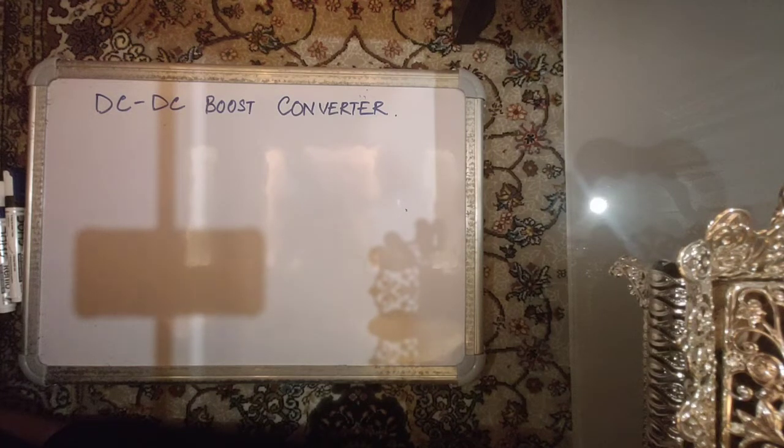We resume our lectures on advanced power electronics. In the previous lectures, we have started with non-isolated DC to DC converters and predominantly discussed the buck converter in detail with the design of passive elements, the role of switching frequency. We have done waveforms for CCM and DCM and the boundary condition between CCM and DCM, and how to design the converter parameters to ensure that your converter operates in continuous conduction mode, the effects of DCM, and a little bit of discussion on the non-ideal buck converter.